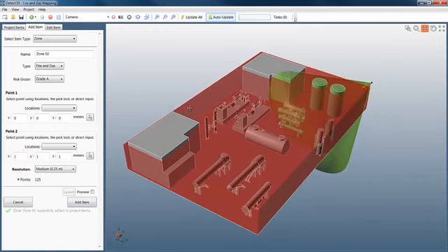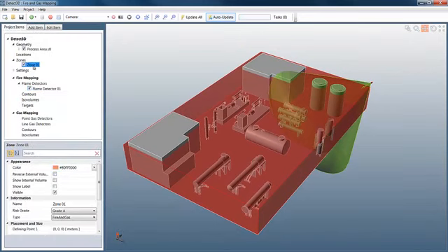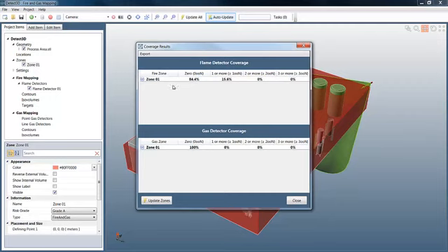The coverage statistics are available immediately to me, and they can be seen by clicking this table. As there's only one flame detector in this project, most of the fire zone has 0 coverage, but around 15% has coverage to one flame detector.